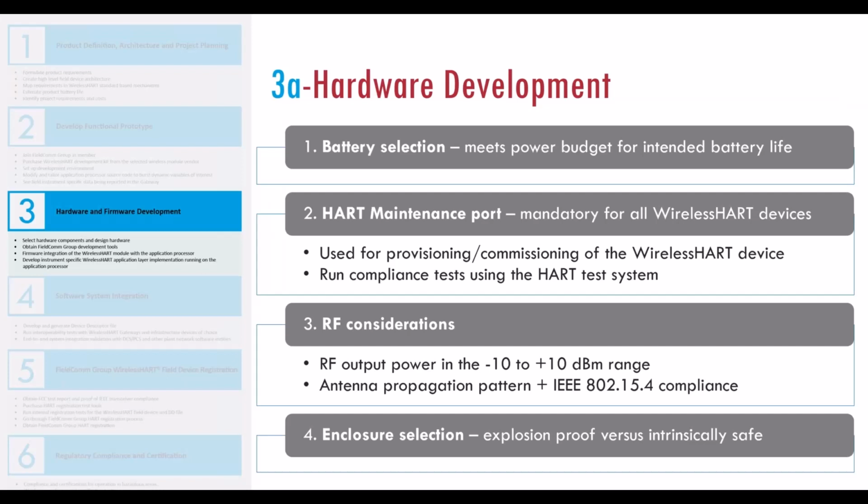So let's move on right along. Now you're ready to start your hardware development. At this point, you would have to go through the battery selection process and select a battery that meets the power budget for your particular instrument. What we typically see is lithium thionyl chloride batteries of various different capacities being used in instruments, or some kind of lithium-based batteries. As mentioned earlier, you also have to include a hardwired maintenance port, an FSK maintenance point,